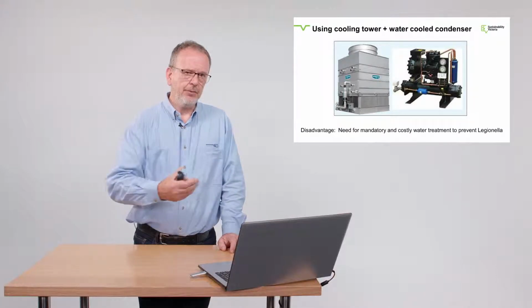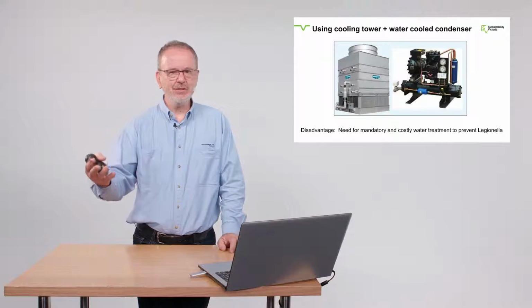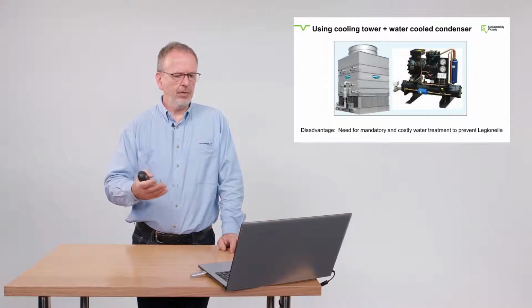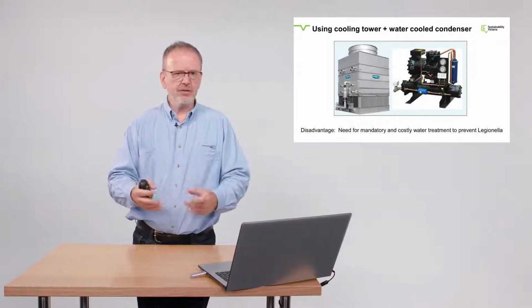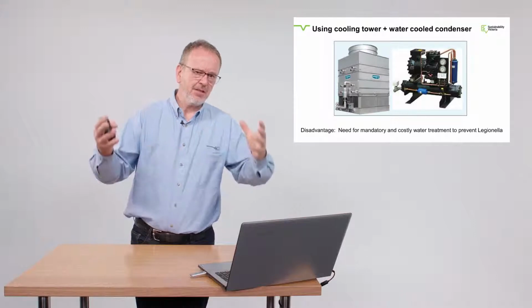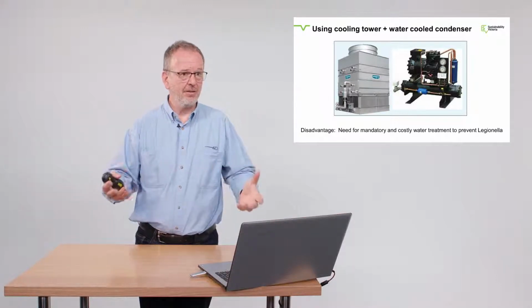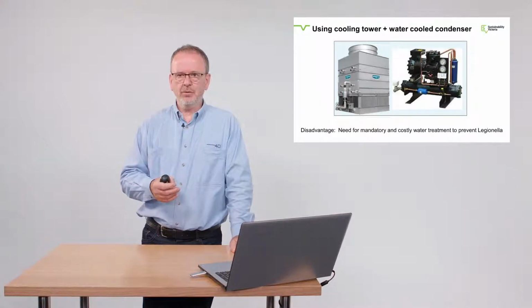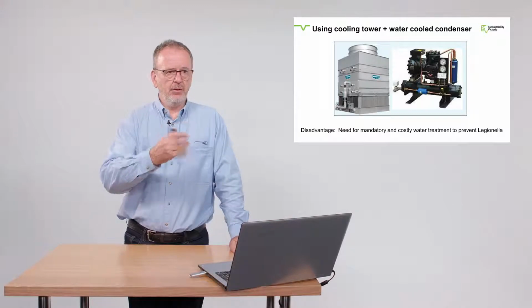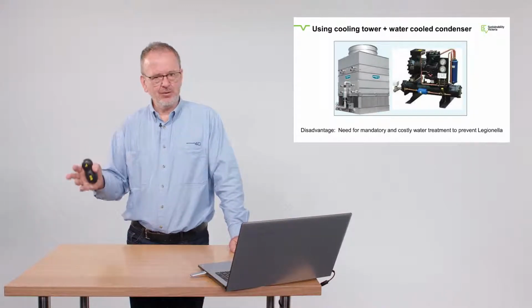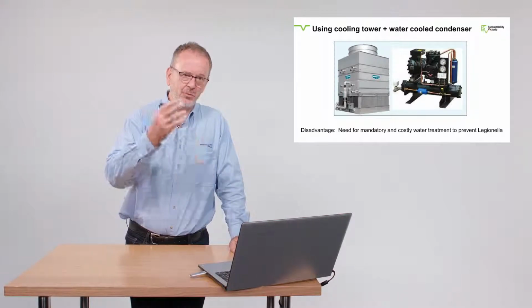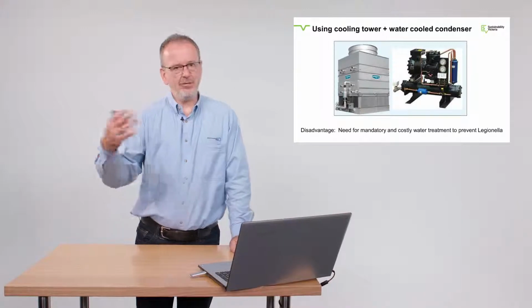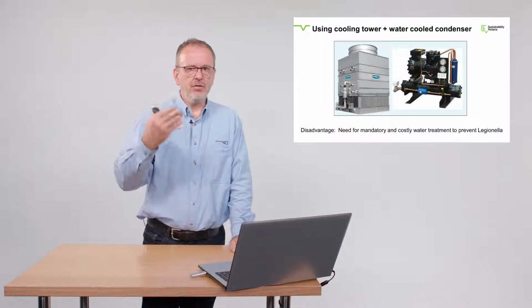And that same building I referred to earlier, they had exactly that, water-cooled systems, and bang, they put the air-cooled systems next to the water-cooled system. Makes no sense. Often on a hotel, for example, the refrigeration is like 10% of the cooling capacity of the hotel. Most of it is air conditioning, and it would make no difference to add it in. I'm not suggesting that you put water-cooled condensers on your butcher shop. That is not a viable idea because it costs money for your water treatment and inspection costs for water cooling. Don't do it only for that reason, but if it's already there, the tip is use it if it's already there.